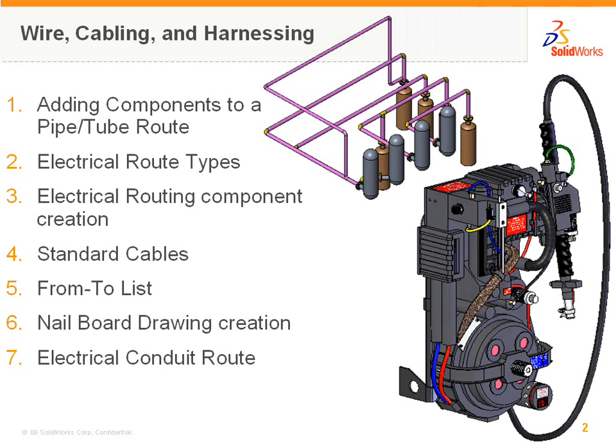We'll go through standard cables. These would be off-the-shelf items, cables that you could run down and purchase at your local hardware store. We'll discuss the from-to list. We'll talk about nailboard drawing creation and finish it out on electrical conduit route.